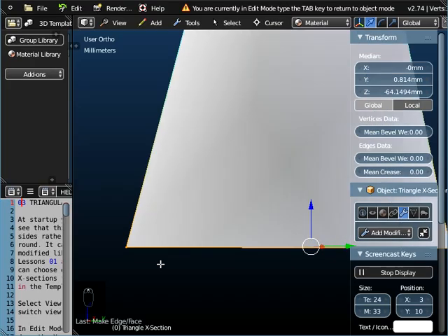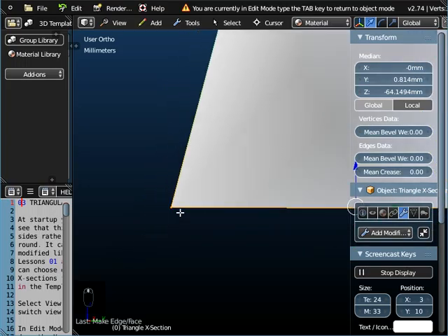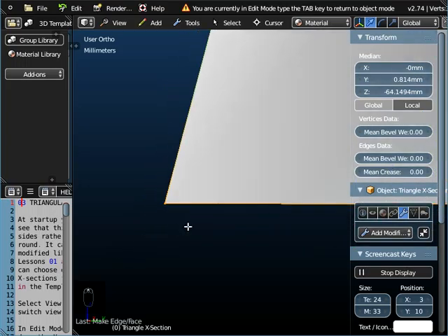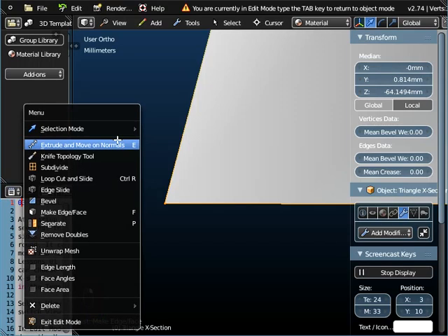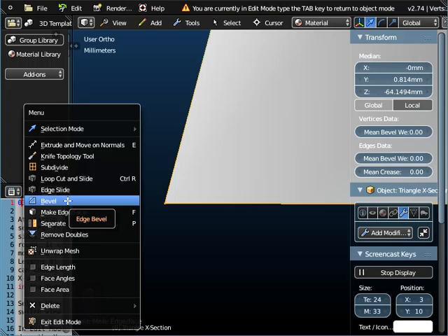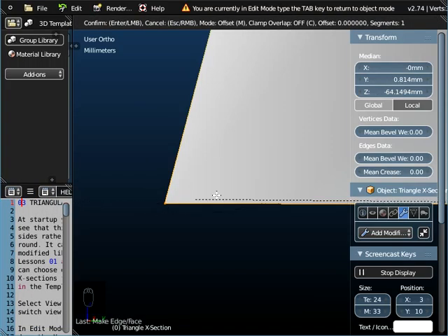Now we're going to modify the bottom of this vase slightly by putting in a bevel. In other words, we're going to straighten it off here first of all, rather than come down to a sharp point at the corner. So I'm just going to reposition the vase on the screen so you can see what we do. So I'm going to click the right mouse button now, and with the bottom of the vase highlighted, I'm going to go to make a bevel edge.